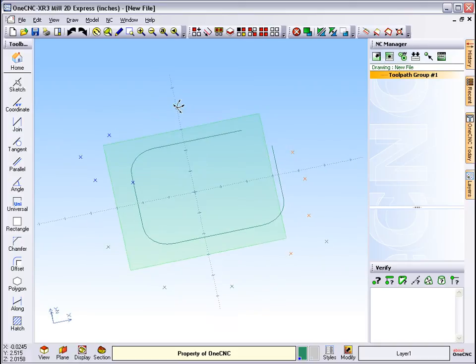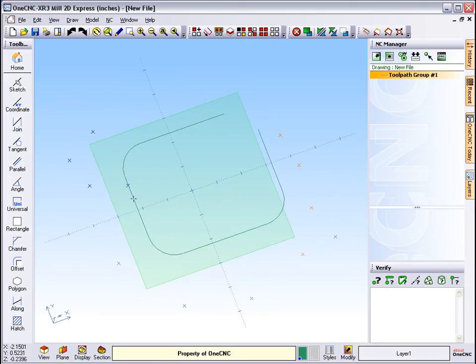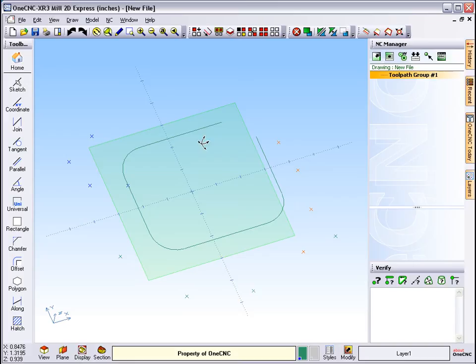Now let's say that I'd like to change the color of these lines and arcs that make this shape right here. So to do that, I need to select the geometry first. So we're going to go up here to chain, left click the beginning, select the direction, and then I'm just going to hit F3 on the keyboard. Everything's selected there.